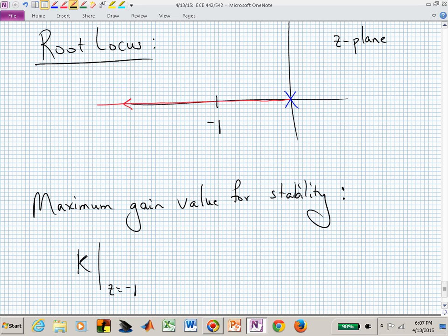In this case, it's going to give you the correct answer, but it's not the right process. Is it clear that the closed loop poles are never going to be at z equal to 1 for this configuration of a proportional controller? There's no way that we will have a closed loop pole anywhere on the positive real line in this configuration of a controlled system.